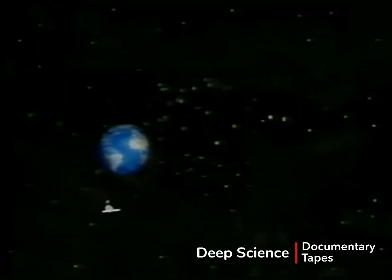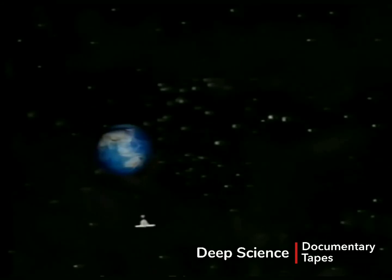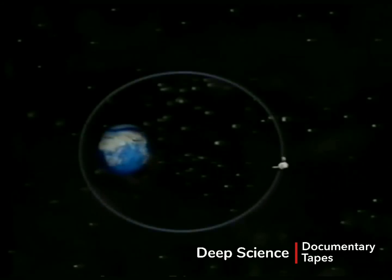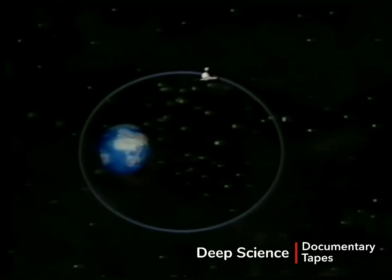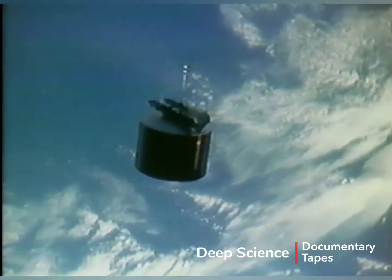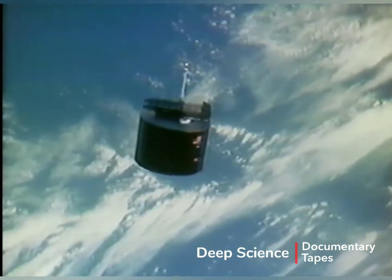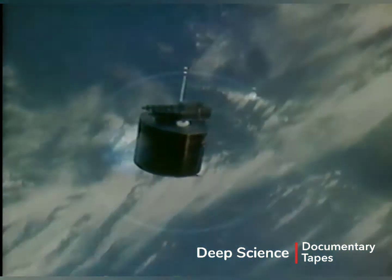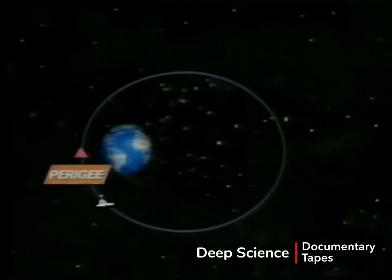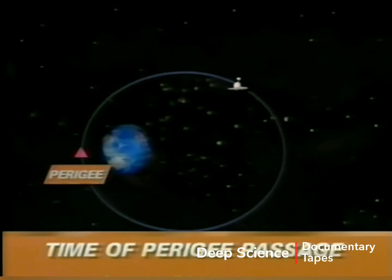The five orbital elements explained thus far describe the size, shape, and orientation of the orbit in space. The final element is a time value used to locate the satellite in its orbit. A satellite moves in a very predictable manner. It stays on schedule. Thus, if the time at which a satellite passes a particular point is known, the time when it will pass any other point can be determined. The particular point chosen is perigee, and the time of perigee passage is the last of the six orbital elements.